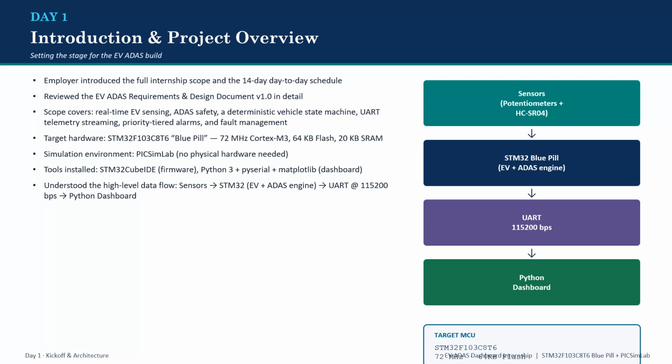By the end of day 1, I understood the full data flow. Sensors feed into the STM32, which runs the EV control and ADAS engine logic, and streams that data over UART at a 115,200 baud rate. A Python dashboard, on the other hand, will visualize everything live.